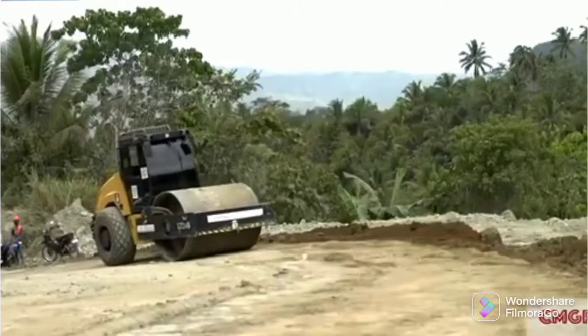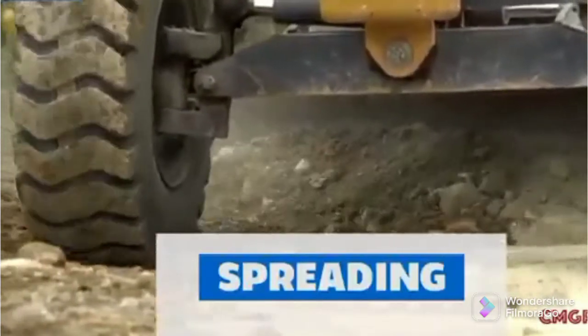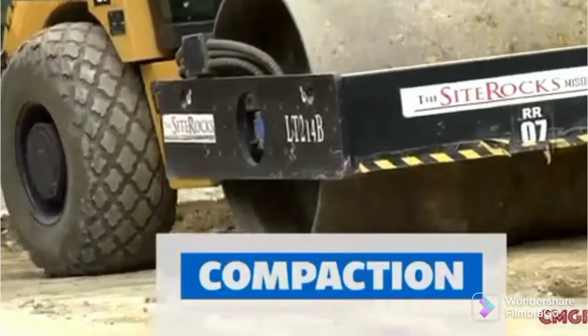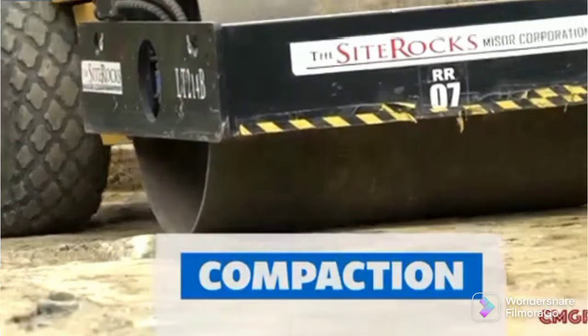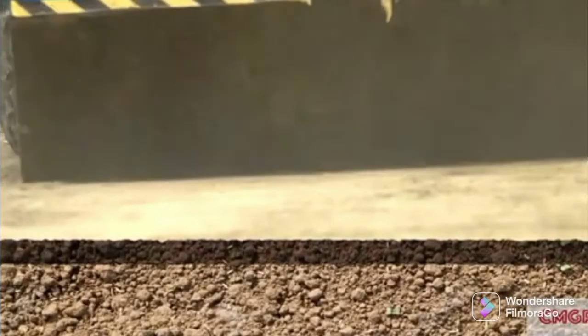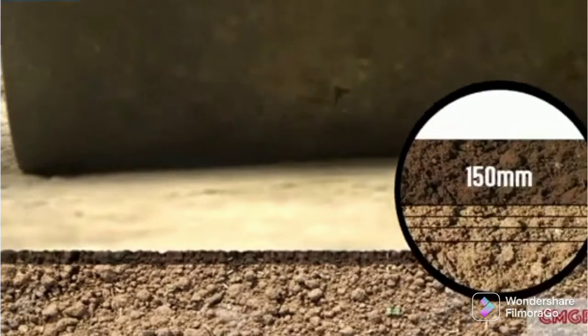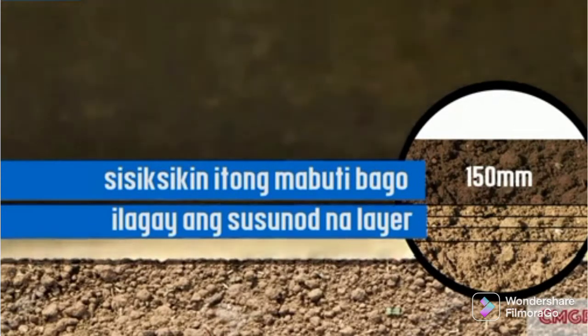Spreading is the spreading of the soil that is compiled, while compaction is a process of increasing soil density and removing air, usually by mechanical means. The size of the individual soil particles does not change. Para sa roadway embankment, inilalagay ang panambak na lupa layer by layer. Ibig sabihin, sa bawat 150 mm na kapal na tambak, ay sisiksikin itong mabuti bago ilagay ang susunod na layer.